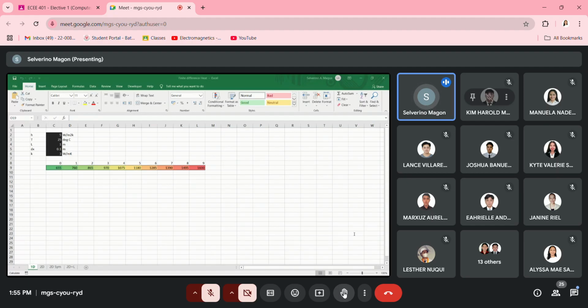You have to recreate this same template that I have here using finite difference analysis, with a reference temperature of 2000. We have the 1600 based on the instruction provided in the manual. So you have to repeat this same thing in one dimension, and then change the rightmost to 1000 and check to see if we have the same temperature profiles.